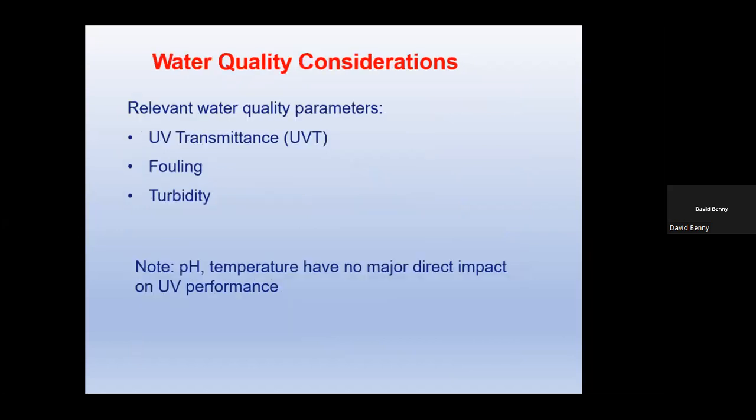So what are the considerations for water quality in a treatment plant that you will have with UV? You have turbidity being a factor, so suspended solids. If you have suspended solids greater than what the environmental regulation will say, which for our part in Trinidad and Tobago is 50 milligrams per liter, and some countries have it at 30 milligrams per liter, UV would be a challenge for that scenario.